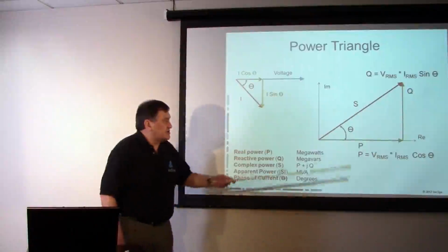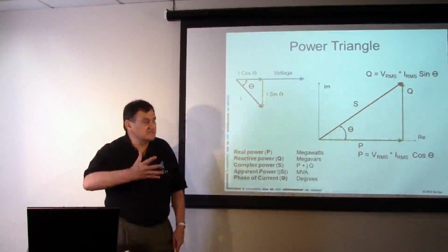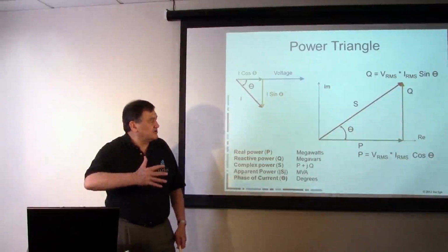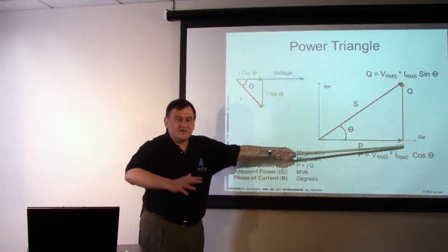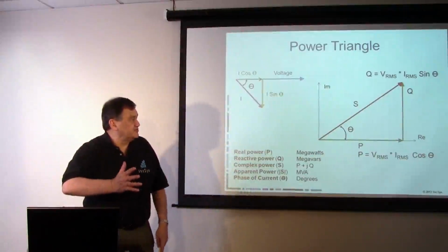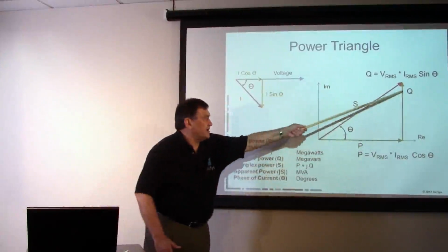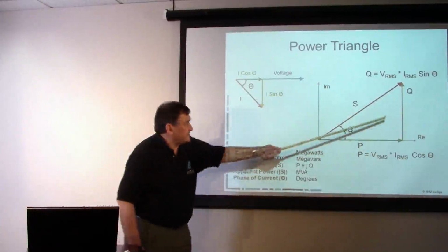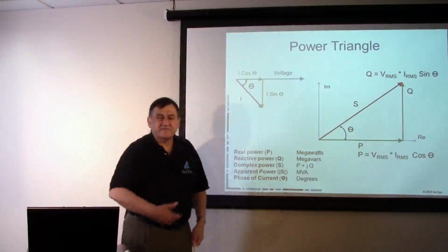So your transmission lines can be heavily loaded due to the combination of the megawatts and the megavars flowing. And you've got to anticipate both those types of components flowing in your transmission lines. And there are cases where you may have 200 megawatts of real power flowing, and you may have, due to the way the voltage is set up, 100 megavars of reactive power flowing down your line. And you can unload that line just by controlling your voltages. In fact, if you bring that reactive power from here down to here, you're going to unload that line significantly.